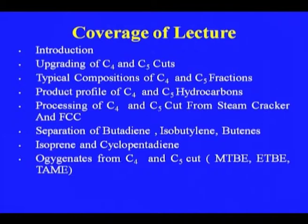Another very important product is the oxygenates. Earlier we started making MTBE or ETBE, the oxygenate from the C4 and C5 cut, especially MTBE. As I discussed earlier, there was a problem with MTBE leakage, and as MTBE is highly carcinogenic, some developed countries have banned its use as an oxygenate. But at the same time, the MTBE you get can be cracked to get pure isobutylene for synthetic rubber. Ethyl tertiary butyl ether is the same, where instead of methanol we use ethanol, and that is what we get from the C5 stream of the cracker plant.